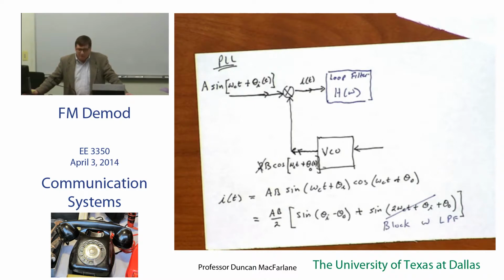And so from a digital perspective, you can spend a lot of time designing the perfect loop filter and implement it and realize it in a DSP really nicely. And for that reason, there's a lot of advantages to working in the digital domain to do all this stuff. If you have to be at high frequencies, optics, RF, and so on, then you can't get away necessarily with a digital filter, with a DSP. It may not be cost effective the faster you go. Although, gosh, if that's not changing these days.